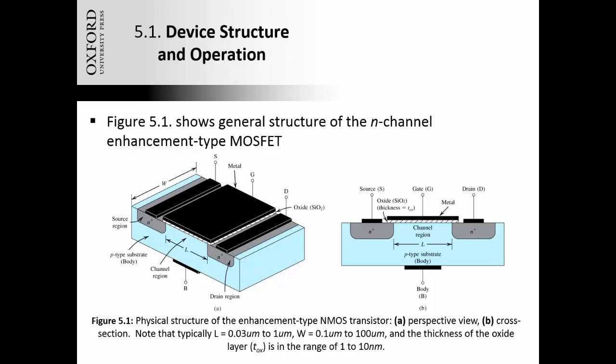And you notice in the figure here, the title: it's an N-channel enhancement type MOSFET. We haven't seen the term enhancement yet, but in general, there are enhancement and depletion type MOSFETs. Once we've studied how a MOSFET operates looking at the enhancement type, it's not a far stretch to appreciate the principle of operation of a depletion MOSFET. However, enhancement is by far more heavily used than the depletion mode type MOSFET, and so we won't actually talk about